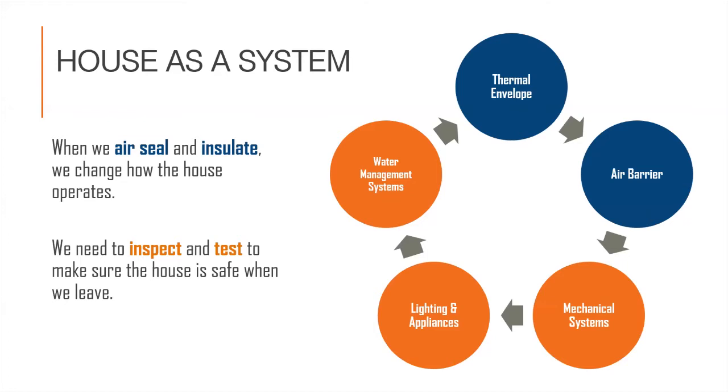Our biggest responsibility as building performance contractors is to ensure the safety of our clients. Every home should be tested and inspected for safety before heading home every evening, in case there are potentially lethal conditions. Dangerous conditions can arise quickly when a home with combustion appliances is air sealed and before pressure imbalances have been addressed.